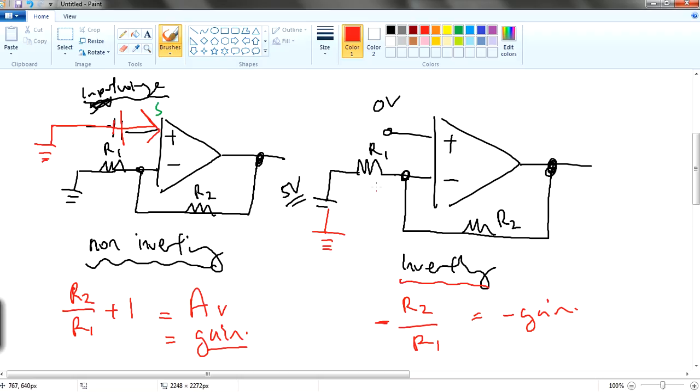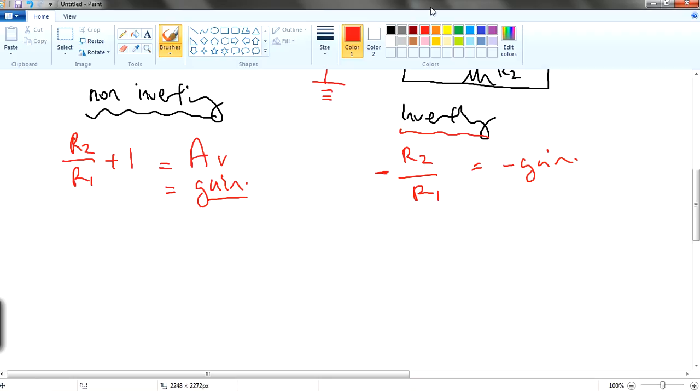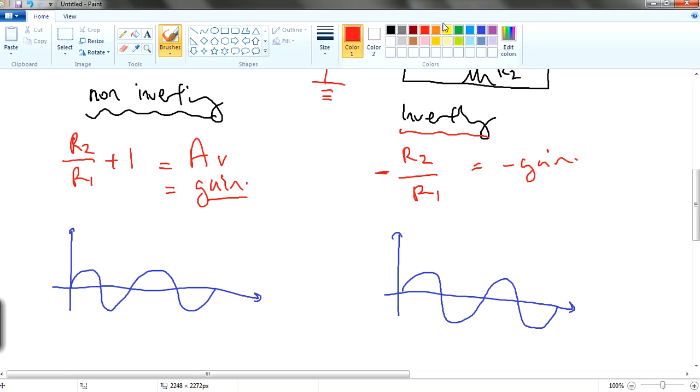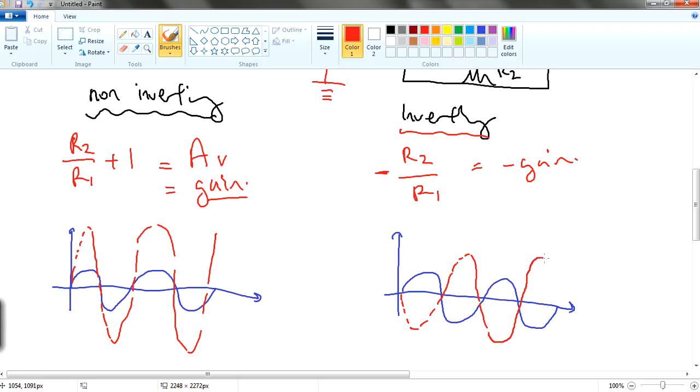You're going to invert. So in a graphical way of drawing, because they may actually ask you to draw out the graph of an inverting and non-inverting. So hold on. For non-inverting, it only amplifies the signal. Okay, you don't change the phase, you don't do anything. For inverting in this case, you actually have an inverted signal over here, right? Nonetheless, you may amplify the inverted signal, so you may have a higher voltage. That's all. So these are the two things you may need to take note of.